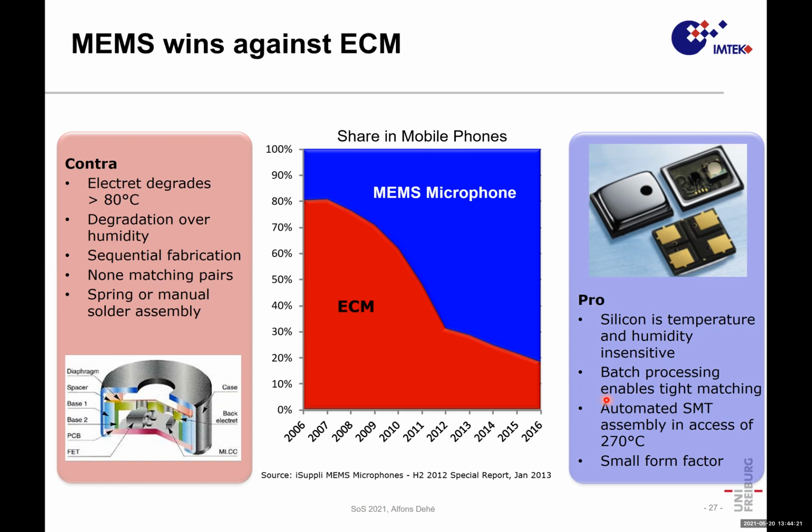And those have the spring contacts. The silicon microphone has SMT capability. So you can put it on a PCB, do the reflow soldering like any other electronic device. And then the argument is we could get smaller in form factors and so on and so forth. So I could argue a lot about those benefits, but customer was hesitant to take over. What you see already, those capsules are cylindrical and have special construction, but the MEMS microphones have totally different form factor.